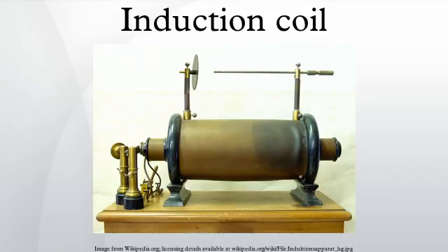To prevent eddy currents, which cause energy losses, the iron core is made of a bundle of parallel iron wires, individually coated with shellac to insulate them electrically.